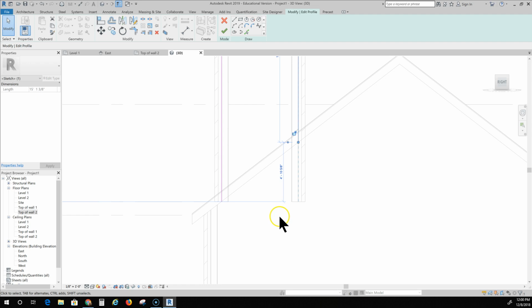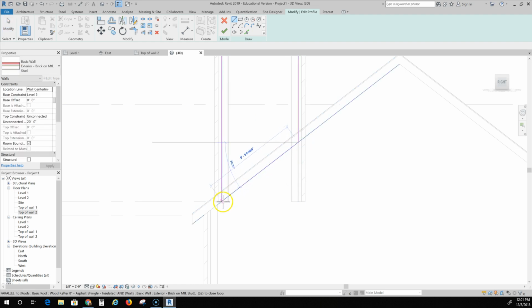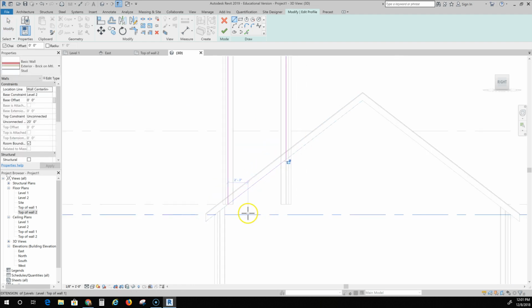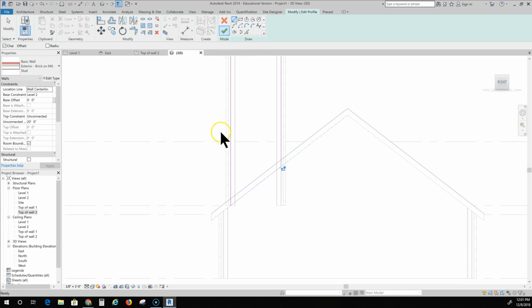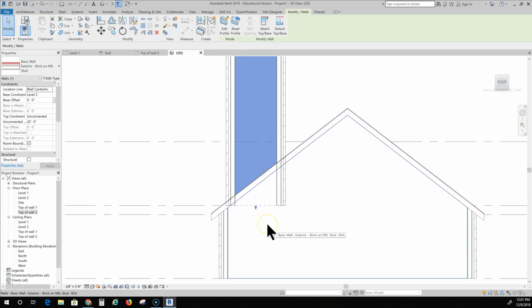I'm going to go to the rafters because I see that this line already comes right to the rafters right there. Okay, so, and I'm going to click on the line tool to draw a new line from here to here. And now that wall is edited, and it no longer sticks down into the living space.